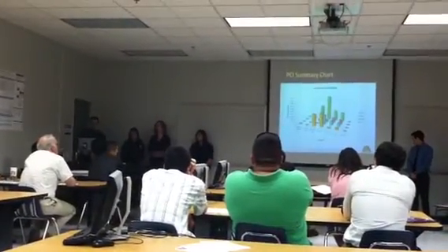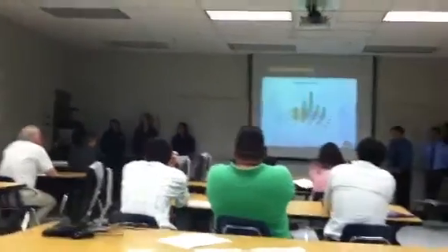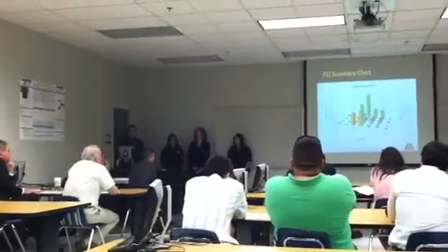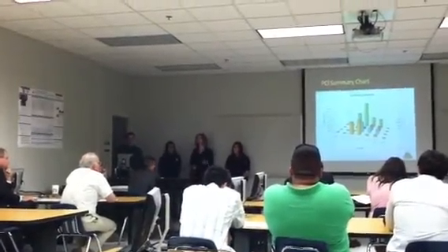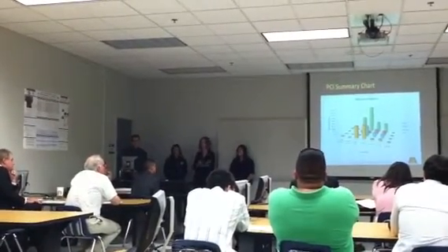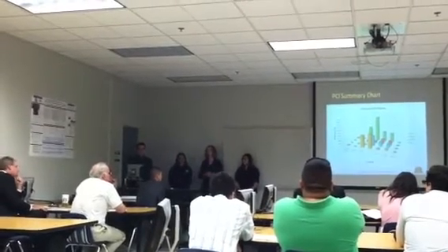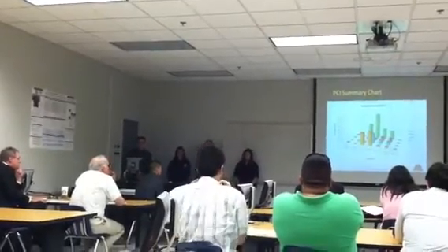We also came up with this graph. It's a summary of condition for PCI. As you can see, all our arterials are in yellow, all our collectors in blue, and residentials in pink. And in the back, you can see all the parts which are in green, and this is a total of all the roads. On the vertical axis, you can see total area. On the horizontal axis, the condition of the roads. And all the conditions range from excellent to failed.